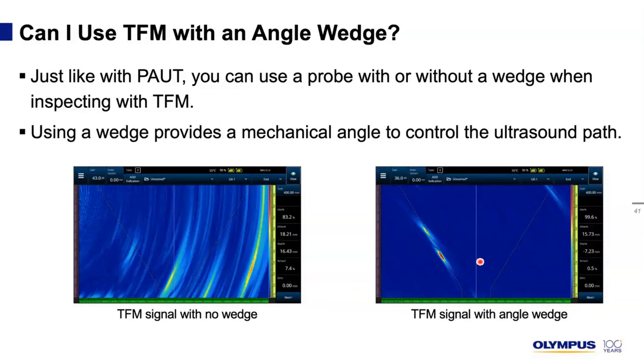Without a wedge, we're using an LL transmission mode or wave set, and we cannot detect anything in there, just noise. While when using the proper wedge and the proper wave set, the indication on the weld bevel is easily resolved. And that just proves that although, yes, FMC and TFM provide great imaging and help to resolve new applications, physics is still physics, and we have to work with it.